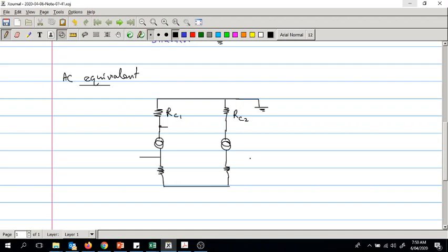Now here what we have is RE and RE, identical transistors and identical resistors as well, and RC. However, the input would be across these two. So this is your V out, where V out is V out 1 minus V out 2, and this is your input. The input actually will be between these two.